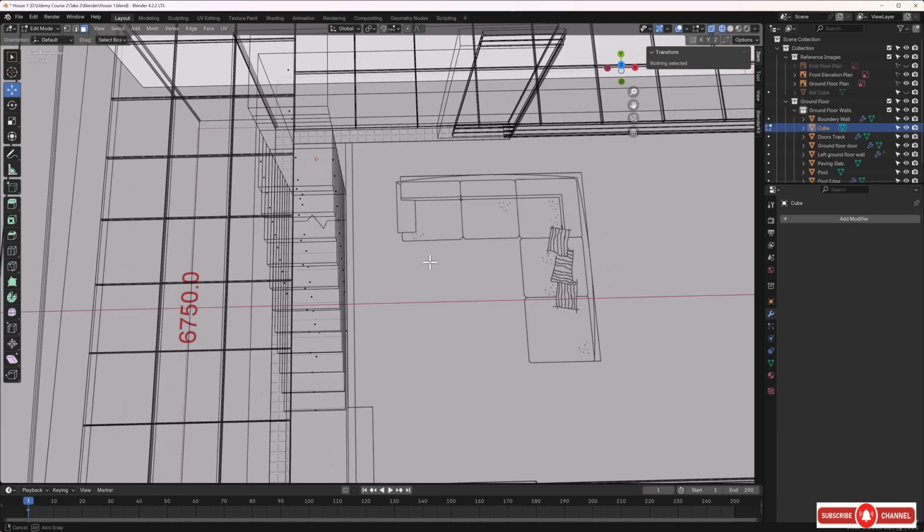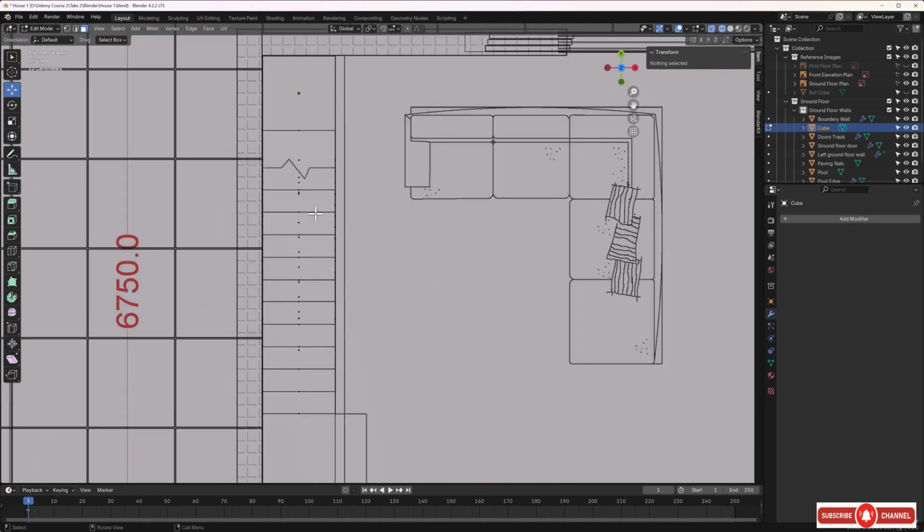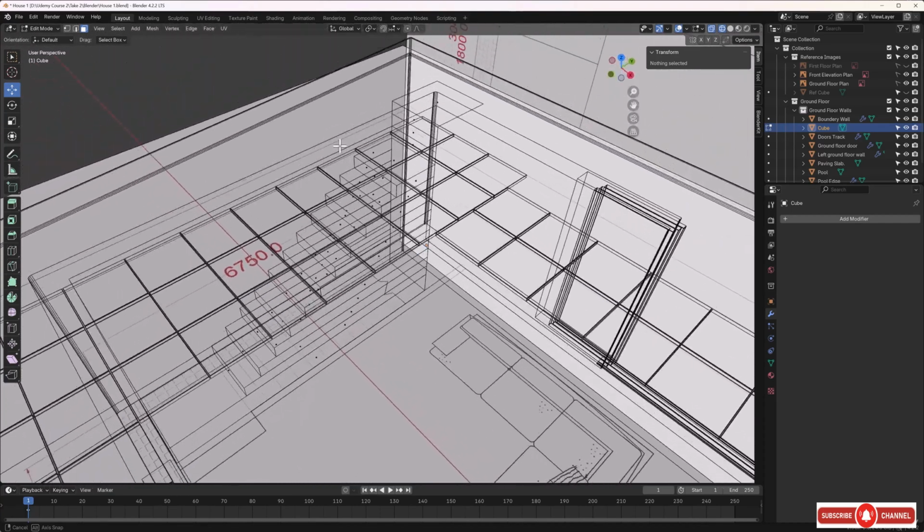Okay, so what this sort of zigzag line here means in the plan is it's called a break of scale. And what that's telling us is that this staircase actually continues, but the information in the plan stops there, but the staircase continues. So what it would have actually done is gone up onto the first floor, which is why it's not seen on this ground floor elevation. So we're just going to make a kind of a few assumptions on this now.